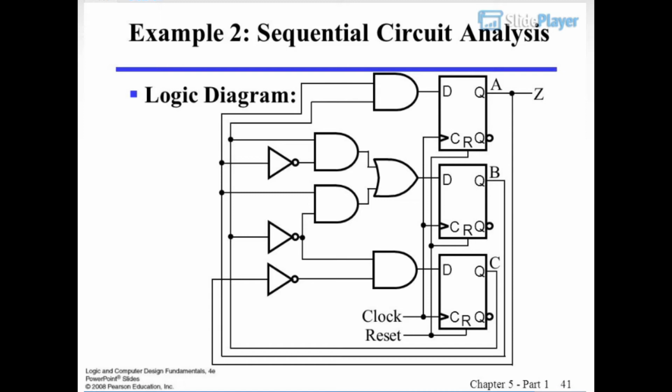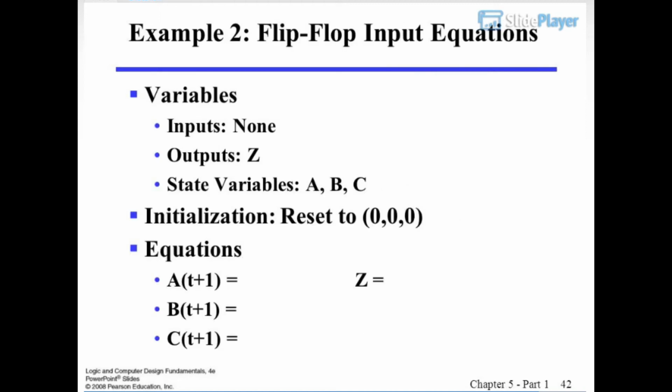Example 2, sequential circuit analysis. Logic diagram with Clock, Reset, D flip-flops, C, R, A, B, and output Z. Example 2, flip-flop input equations. Variables: inputs, none. Outputs, Z. State variables, A, B, C. Initialization, reset to 0, 0, 0.